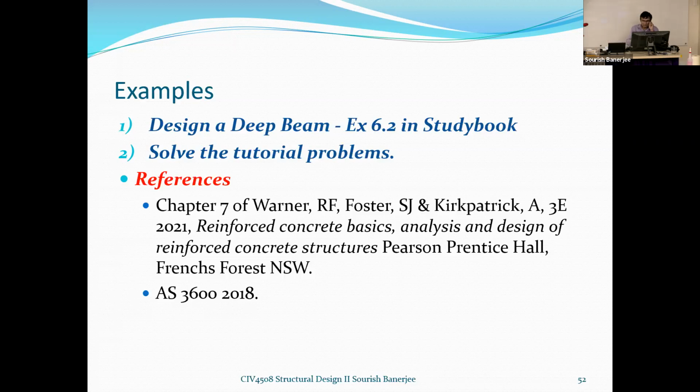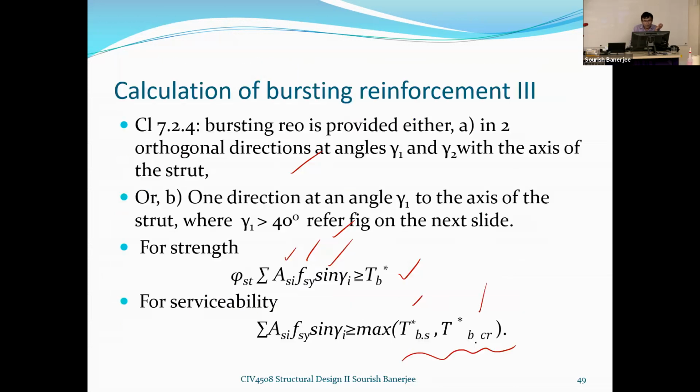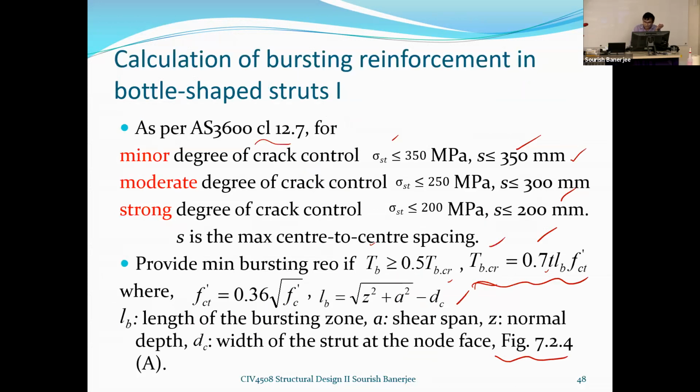I will quickly make a comment before I stop. When you're looking at the bursting force, remember, if you think of the plane of the screen, you have this strut. For example, this is the strut, and somewhere you have this bursting happening because of the reduction in this area. So there is a change in the cross section, basically, it's getting a divergent type of stress field.